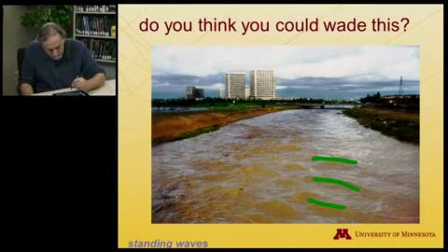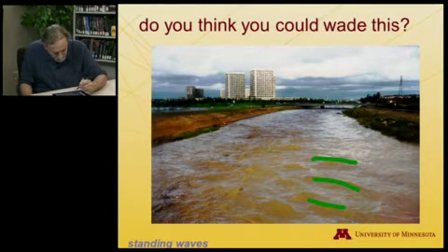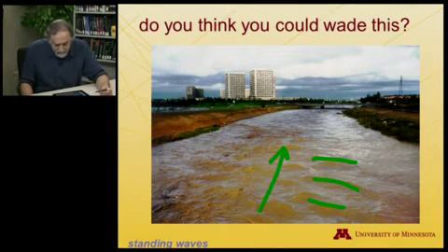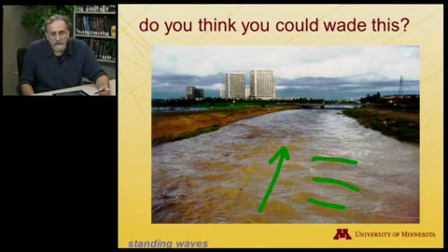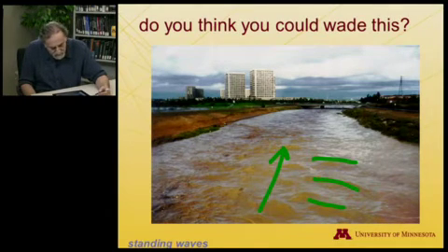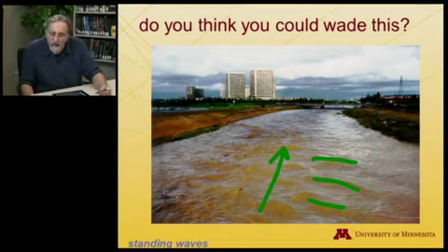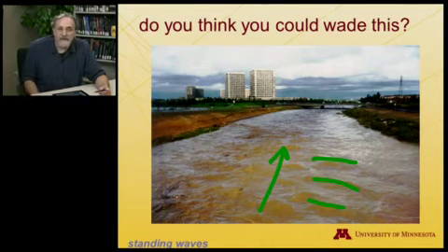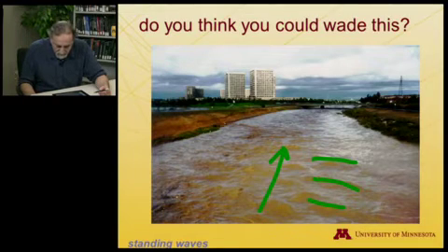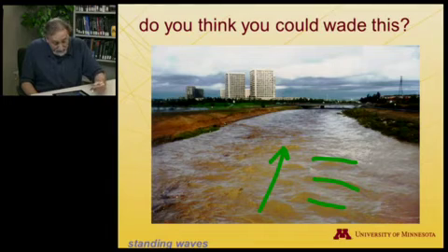These are called standing waves, and the flow is basically flowing through the standing waves, like this. From the size of these waves, you can deduce that this flow is something in the realm of a meter deep. It might be half a meter, it might be a little more than a meter, and that it's moving at a speed probably of a couple meters per second. That's much too fast for you to walk in. You would be knocked over right away. If you did that, it would be quite hazardous, something definitely not to try.